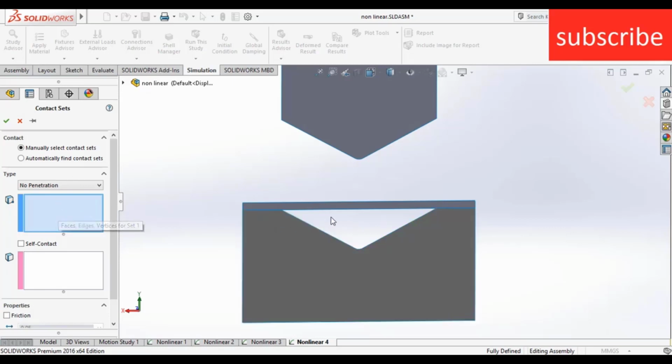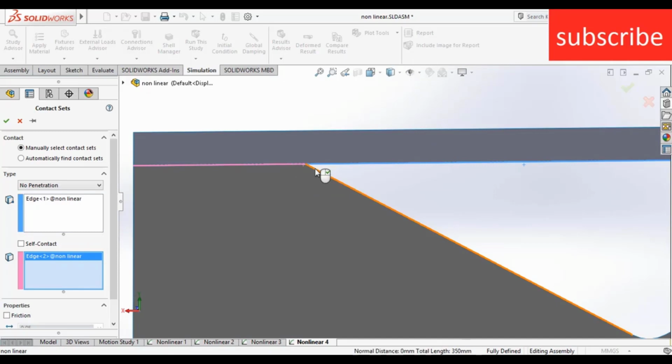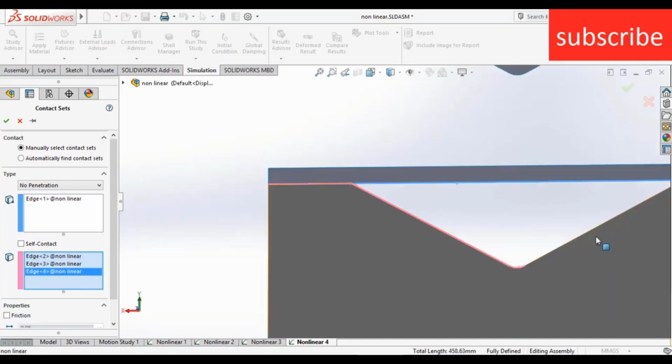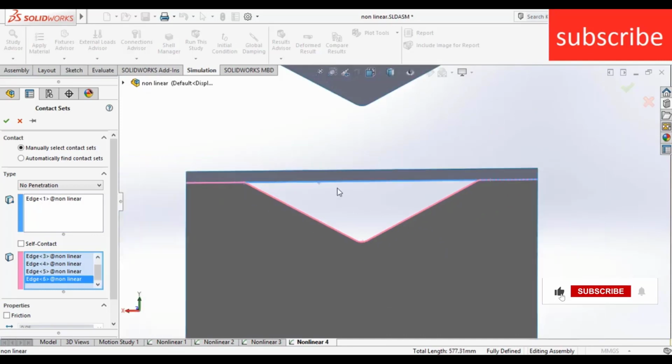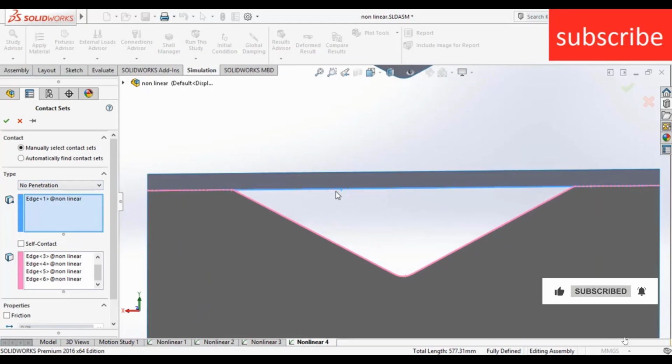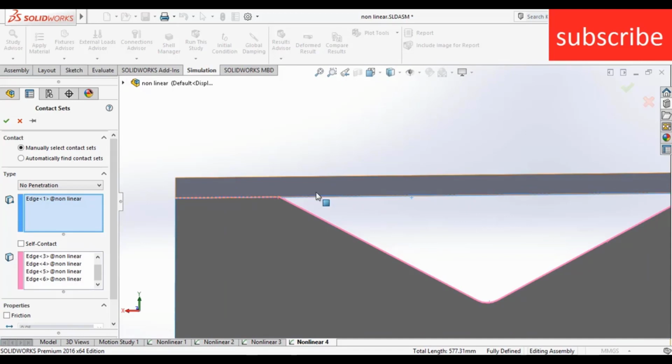So first thing it asks is to select the face. So select the bottom of the plate. Now select the top of the die. Make sure you select all edges. Here you see that I selected in one the bottom of the plate, and in another I selected the die top. The reason is that I am creating a set so that my software knows where there is no penetration. When I do the simulation, SolidWorks now knows that there is no penetration in these bodies.